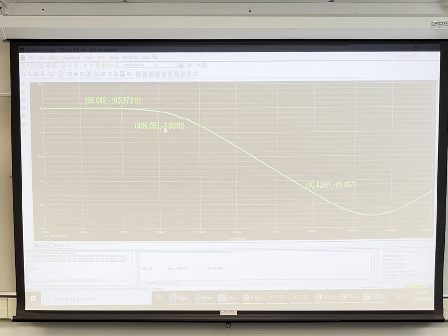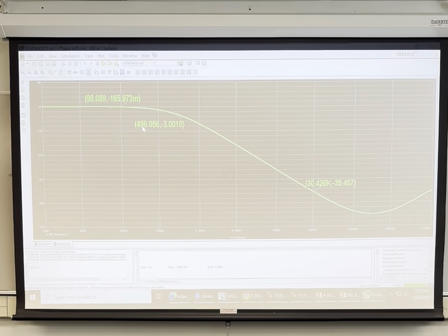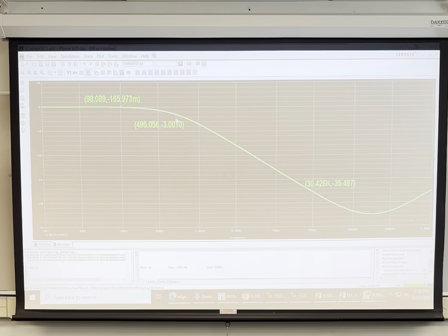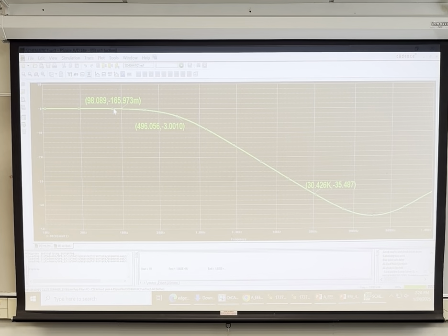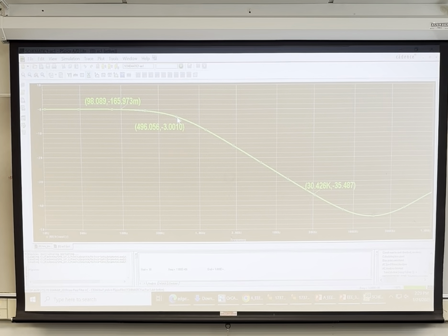So here it's decided to let the cutoff be 500 hertz. You notice 500 hertz is far enough away from 100 hertz, so it doesn't reduce the 100 hertz. And 500 hertz is also at a point where it helps to reduce the interfering signal, which is 30 kilohertz.